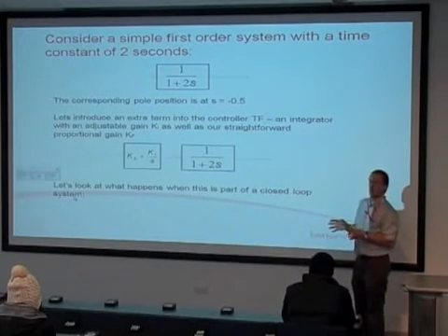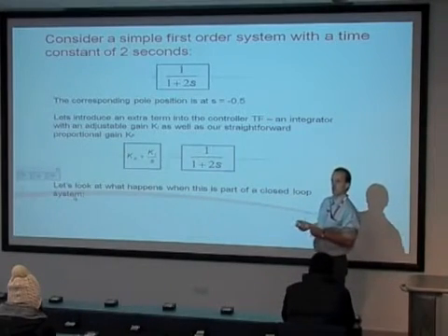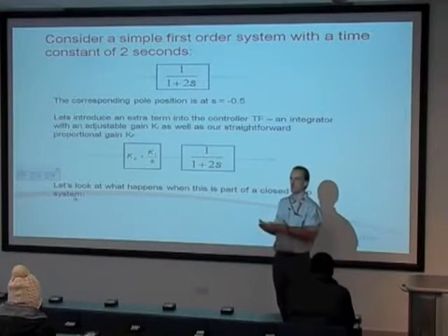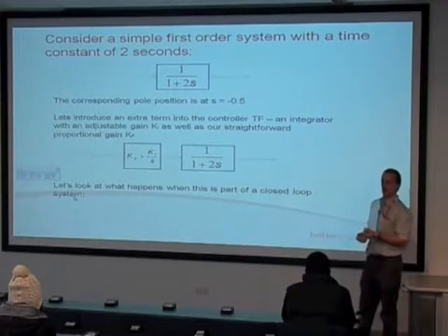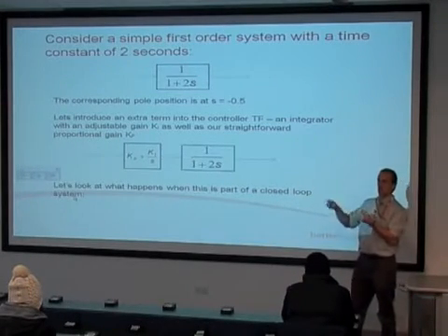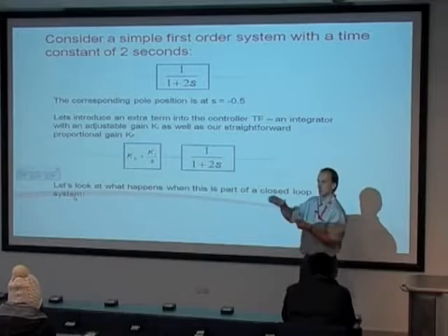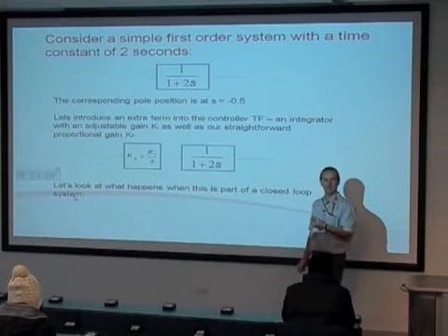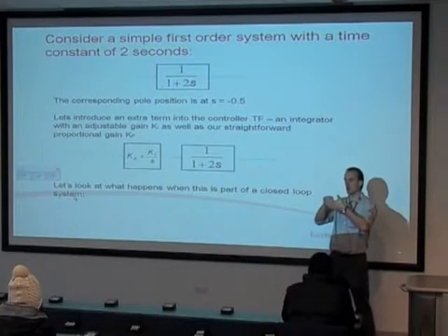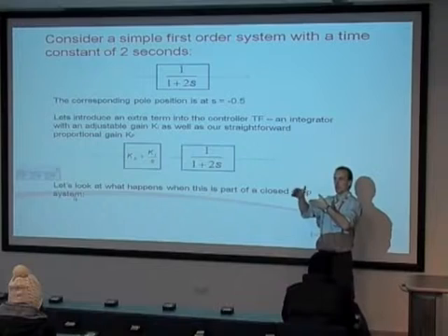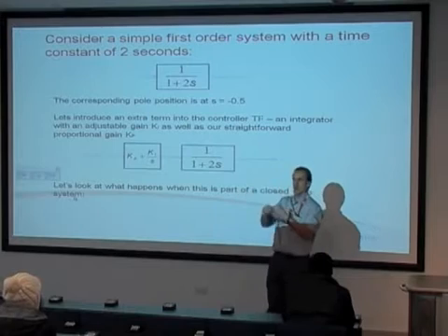What we end up with is a signal coming out which is the error. How wrong is the speed? It can be positive or negative depending on whether I'm going too quickly or too slowly. So I've got a signal which I call the error signal, and I use that signal to drive, let's say, a motor that works the throttle pedal or the throttle butterfly. If I'm too fast, the negative feedback will come out negative, and I'll unwind the throttle to slow the car down. And if I'm going too slowly, then the error signal is positive, and I'll wind the throttle open.